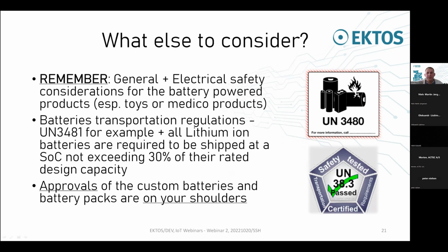So yeah, what else shall we know? That was it about the main topic of the presentation. What else shall we know about battery powered products? Basically, it's the general and electrical safety considerations we shall do. This is especially important for toys and medical products, of course. Then there are some battery transportation regulations, and for example, for lithium-ion batteries, you are not allowed to transport batteries with a SOC exceeding 30%. So it shall be handled in a proper way. And of course, approvals for custom batteries and battery packs are on your shoulders. So if you decide to go for a custom battery or custom battery pack, you will need to take care of it.